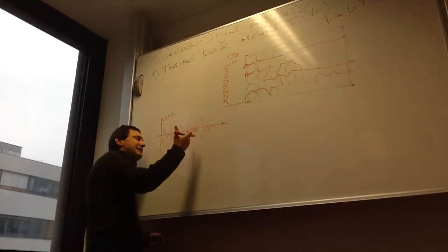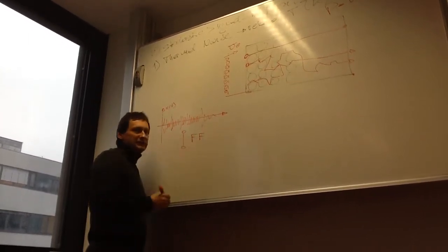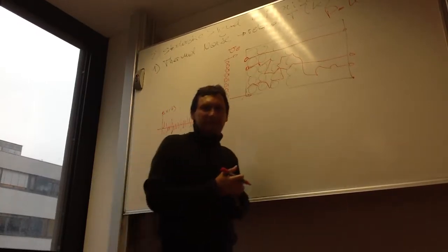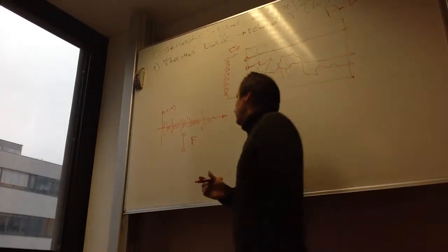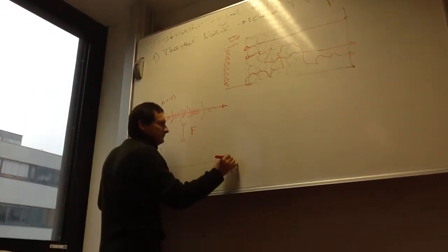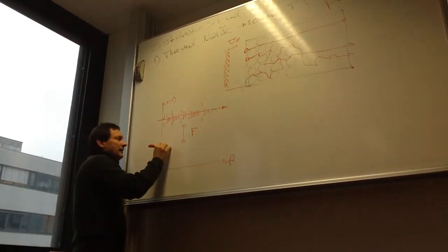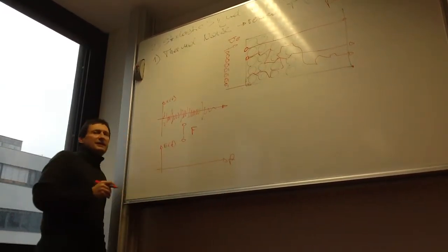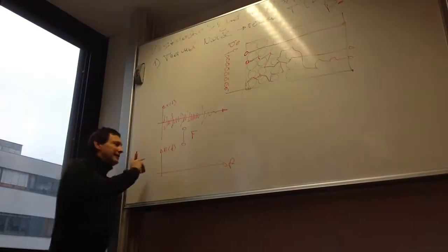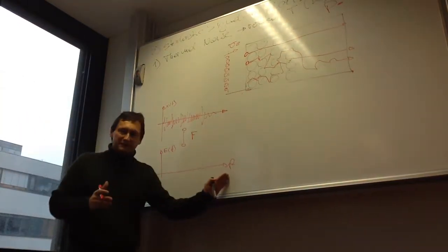If we are getting the spectrum of our signal, we're doing a Fourier transform. It must not be fast, it can also be slow. Then we have the spectrum of our signal. So it's frequency. And if we are monitoring here the energy, what we are interested in is how the energy is distributed over frequency.